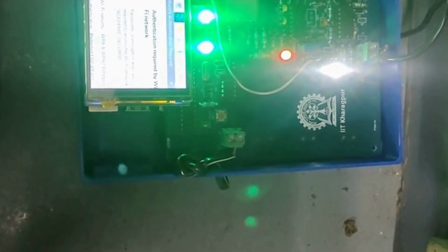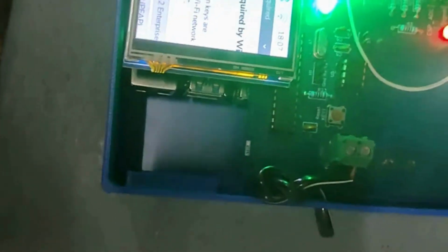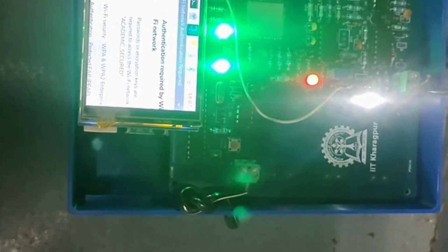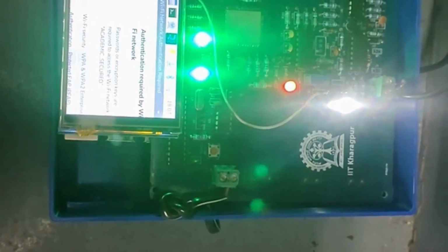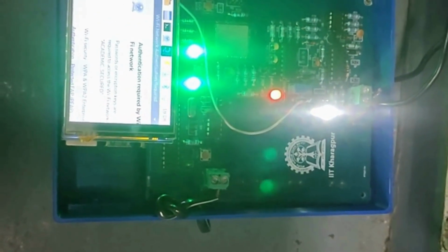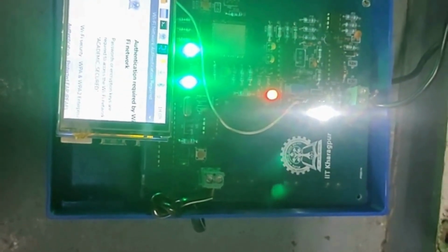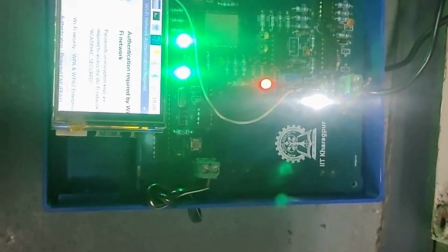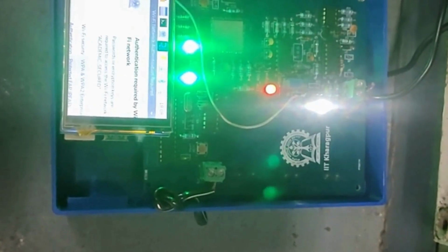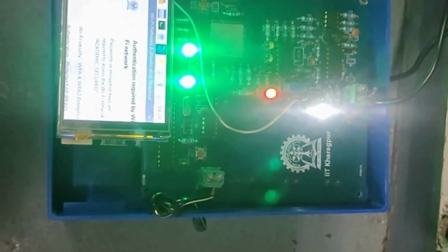So this is our edge device. You can see this edge device has two parts. One is the signal conditioning circuit and another is the edge where the Raspberry Pi is connected. The Raspberry Pi handles all the computation and all the algorithms that are deployed in this device, and it will estimate the rotor slot harmonics. Then it will derive the slip, speed and the efficiency the motor is operating at, and it will also detect various kinds of faults that are currently present inside the motor.